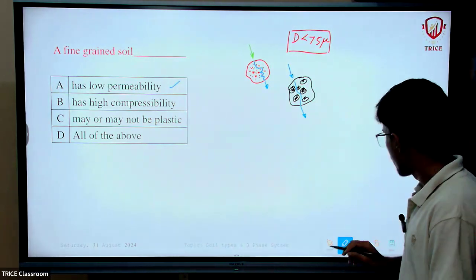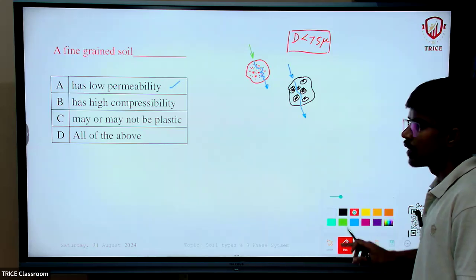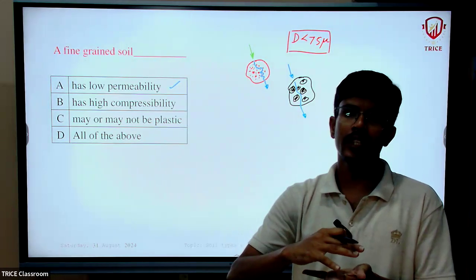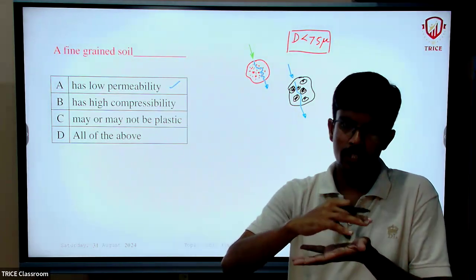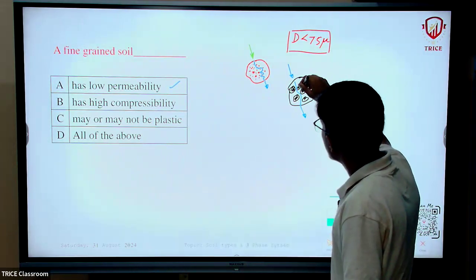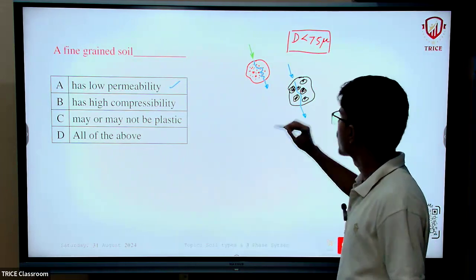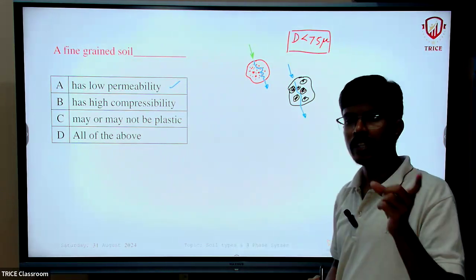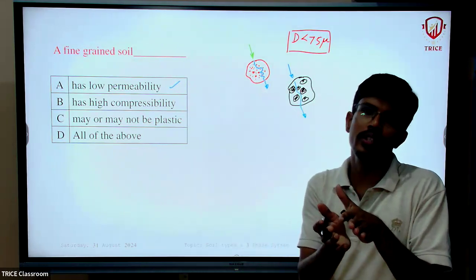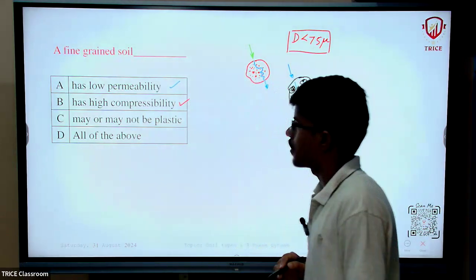Okay. So when we have the black cotton soil, as we know, due to its plasticity in nature, this soil is compressible. It will compress a particular depth under lesser load. If you take a certain load, you can observe certain deformations: very minor for coarse-grained soils, whereas when the same pressure is applied on clay type soils, you can expect heavy deformations. Okay. So the second option also matches.